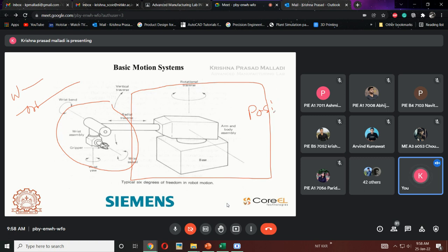So this position axis is generally used for the basic robot movement. Which means with the help of the position axis only you are reaching the tool, or you are reaching the workpiece. So if there is a workpiece here, from this you need to pick a path. Your robot is at this location. Coming from this location to this location will be done by the positional axis only. Which means base, shoulder as well as elbow. By these things only you need to do this operation.